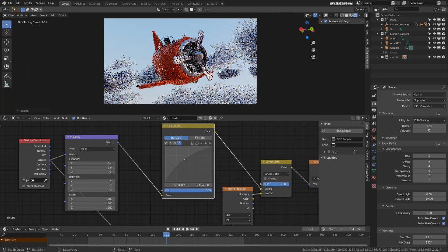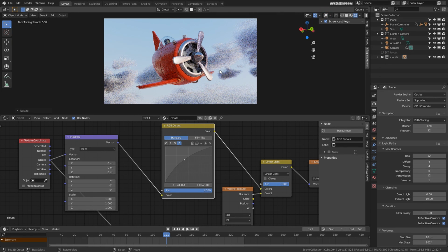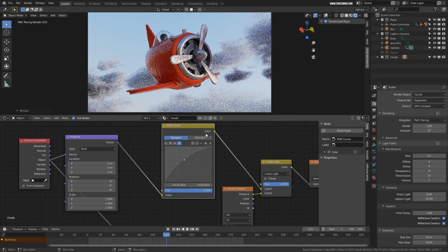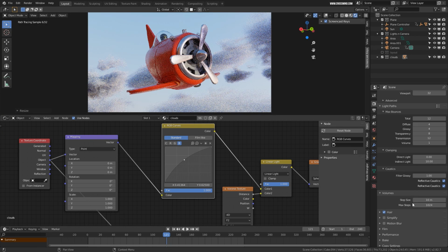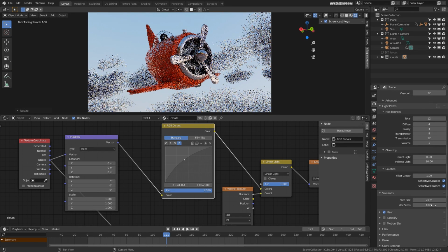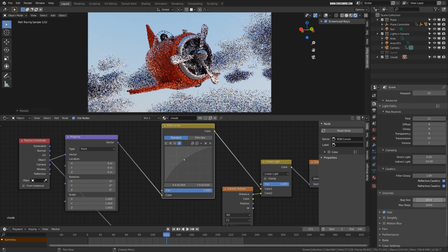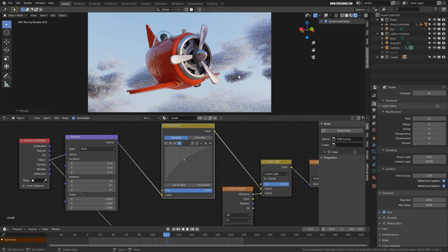So yeah, looking at your computer configuration, if the scene is getting too heavy, you wouldn't want to add so many clouds, and also you need to adjust this parameter if it gets really difficult to render. But don't increase it so much that the clouds start to look really flat. If you increase it too much, the density will make these appear really flat. So I'll keep it at 10 for now, and now let's start preparing this one for render and take a preview.